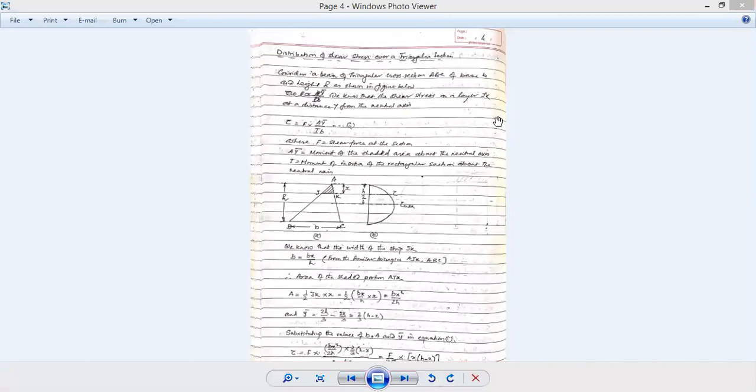Now, so far we have discussed the shear stress and bending stress induced in a beam as a result of external forces acting over the beam, whose line of action is perpendicular to the longitudinal axis of the beam. As an effect of the presence of these external forces, the beam gets bent in different ways at different sections, and the whole beam is stressed by tensile and compressive stresses along the longitudinal axis.